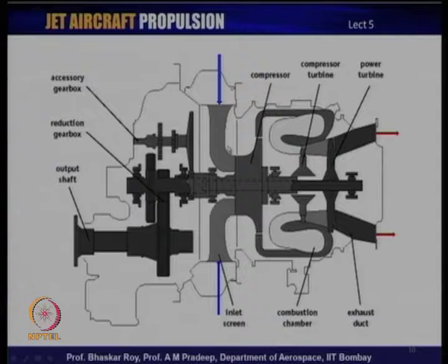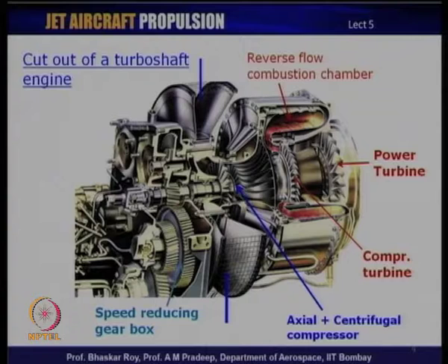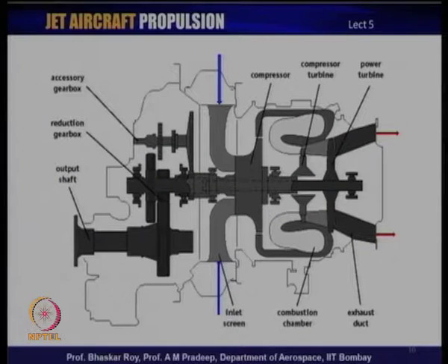So, you have a sidewise inlet of air going into the basic engine, and quite often the exhaust could also be sideways like this. As I mentioned, they do not produce any direct thrust. Essentially the exhaust gases have had all the energy taken out by the turbine, and they simply go out without any power or residual energy left in them. They go and mix with the atmosphere. So, this is a simple schematic of the kind of engine we just had a look at. This is the basic engine, a picture, and this is just a schematic of its layout inside that engine.